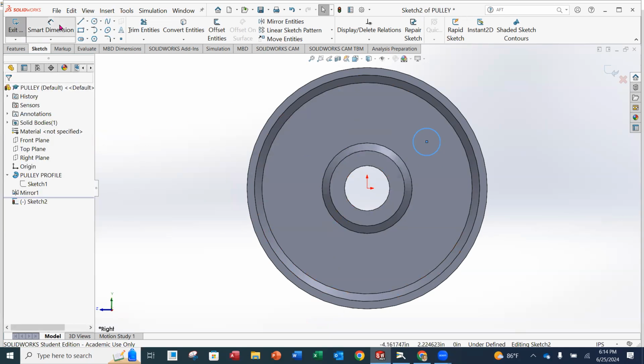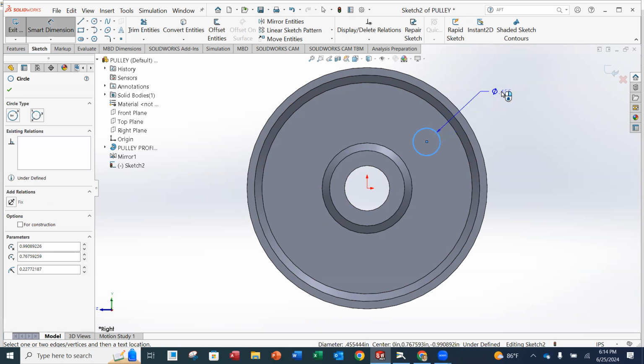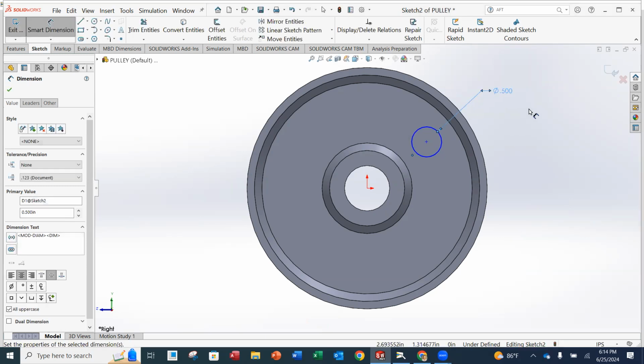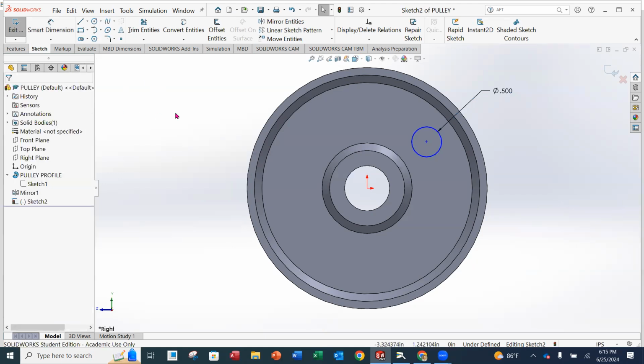Okay. First thing I'm going to do is I'm going to grab the diameter, and the diameter is going to be, I'm going to peek ahead, a 1/2 inch, 0.5. Okay. It's going to be a 1/2 inch, but we're not fully defined. We have to locate this, but the location of this is not going to be an X and a Y value. It's from the origin. We're actually going to put in an angle. Okay. And to do that, we need to add some what we call construction lines. Okay. So this is something that's new. I'm going to hit OK here.